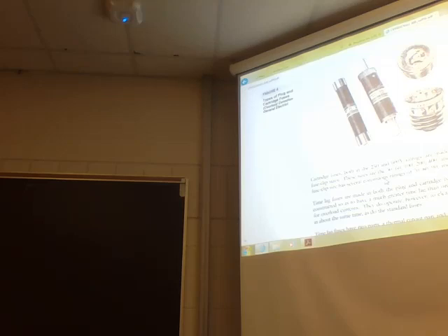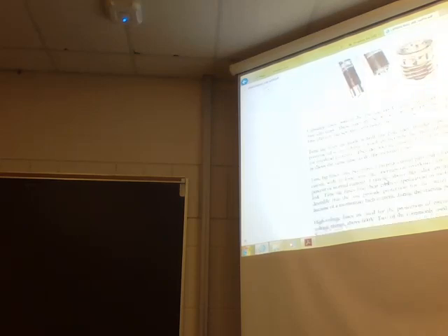Time lag fuses are made in both the plug and cartridge fuses. These fuses are constructed so as to have a much greater time lag than ordinary fuses, especially for overload currents. They do operate, however, to clear short circuit currents in about the same time as do other fuses. Time delay fuses are used more in motor circuits to allow for the high current from the startup.